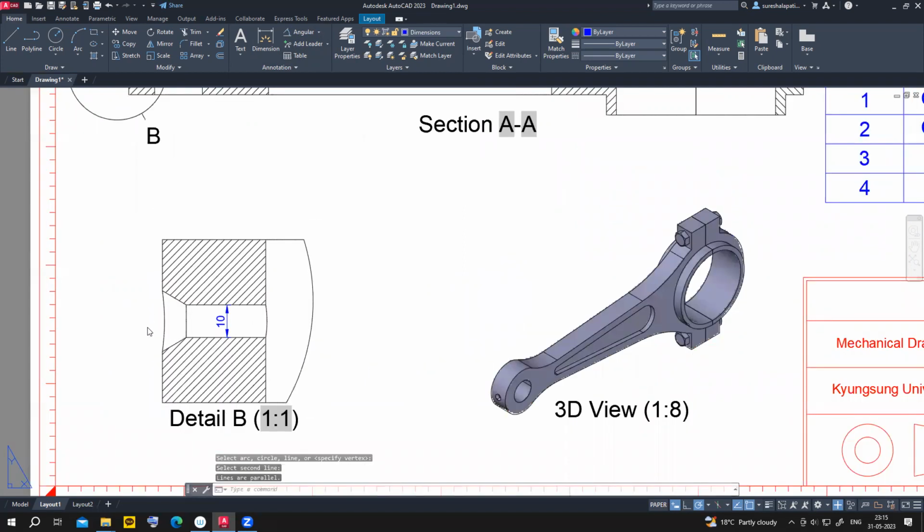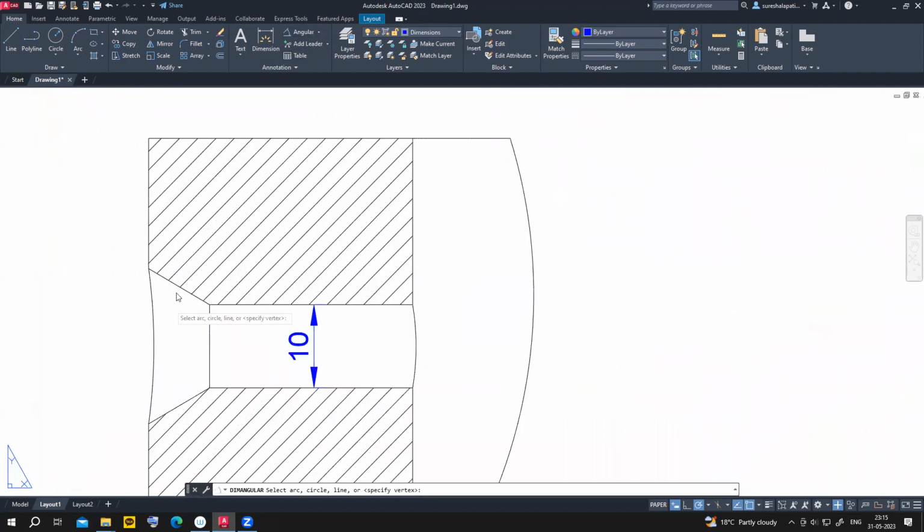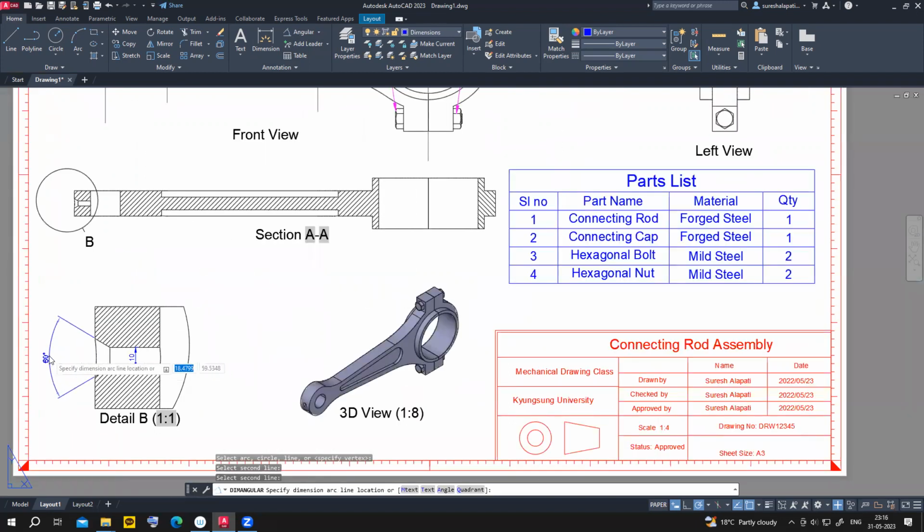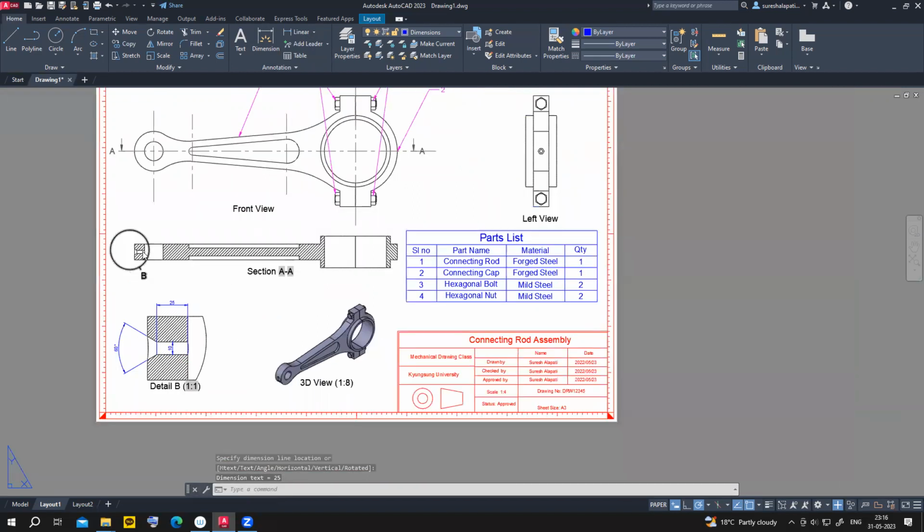I select this line and the second line is not clear. So select this line. Okay, more clearly. Select this line. Okay, yeah, this line. So two lines, these two inside. So angle 60 degrees and also specify the length, right? So 25. Okay. So those are the dimensions of this keyhole, right? Keyhole is very small. Countersunk hole. Okay, not keyhole, sorry. So a lubricating hole.